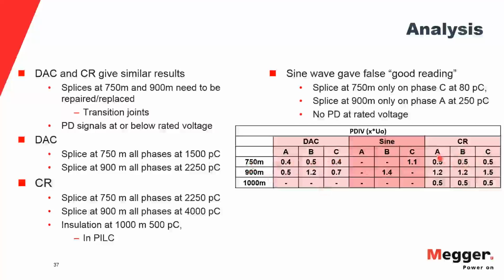So the conclusion to this is certain types of defects are very sensitive to the voltage wave shape, specifically the slope at polarity reversal. In these cases, if the weak spots can be detected at all by VLF sine, they do require a much higher voltage, and they tend to give a much lower PD result back.